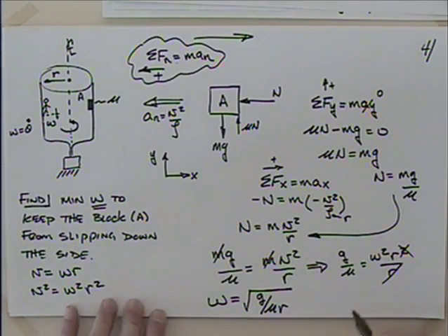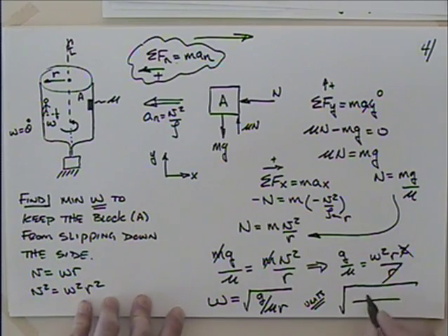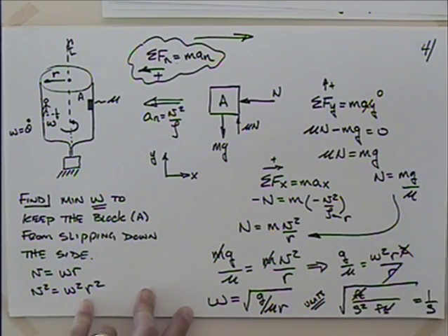Now, what do the units look like in this thing? Underneath this radical, if I have English units, I'm going to have what? Feet per second squared for the acceleration. Mu does not have units. R would be presumably in feet. Is that right? So I get to cancel that, and you take the square root of 1 over second squared, and you have 1 over seconds, which is radians per second, right? Radians per second. So the units seem to work out on that.